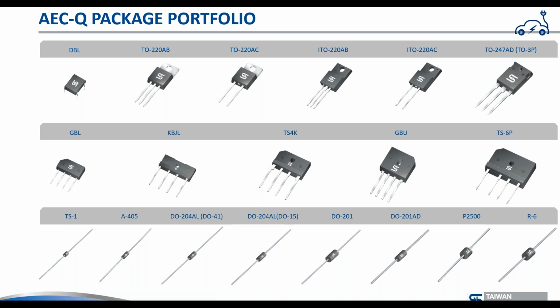The only thing is that they're not here because they're obviously not AEC-Q qualified. For example, MELFs, but they're still around. They were considered dead 30 years ago, but they're still going. And I've even seen a PCN for a TO92 package last year. So those are the two dodgiest packages, and TO92 is not even a rectifier package. But the obsolescence is caused more by the front end in our type of business than the back end.